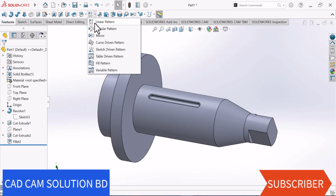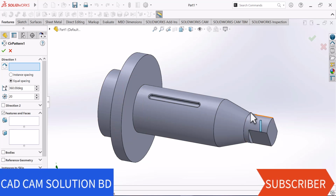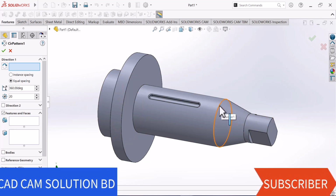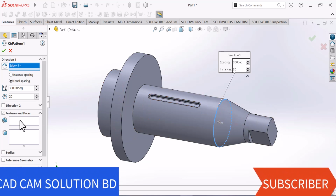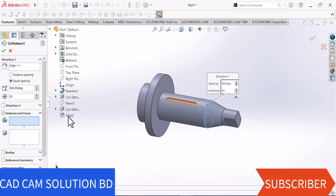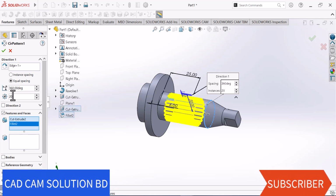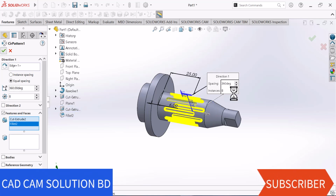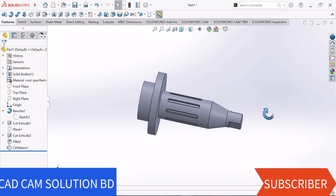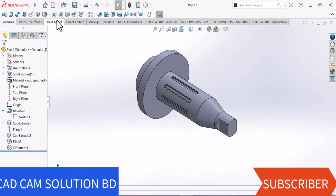Now go to here, select circular pattern. Now here select feature and face. Now here select cut and fillet. Now give the value here 8. Okay. Now go to isometric view.